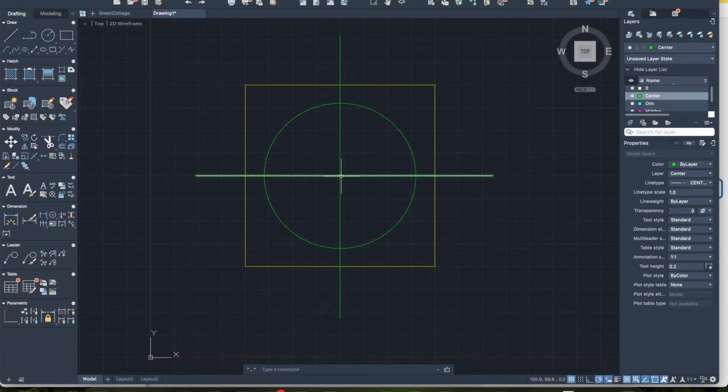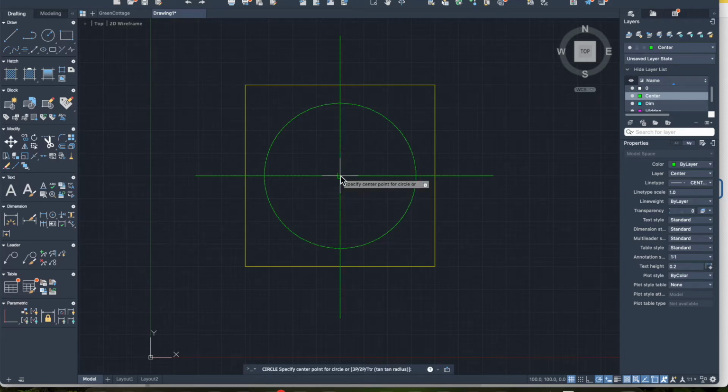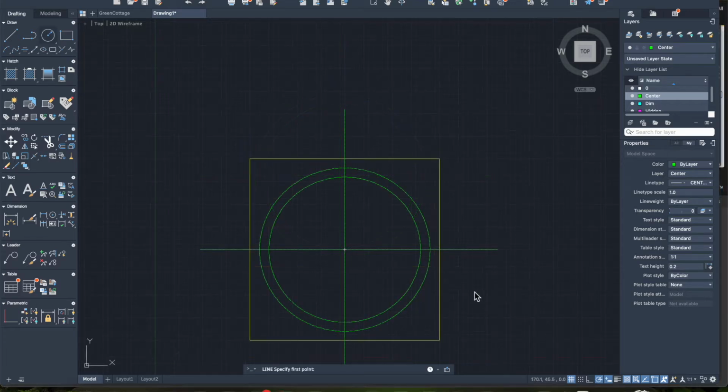And then you can click again in the center. There's different ways to do this, but this is the simplest way to explain. You click again, so hit spacebar to repeat the last command, click here, and this time I want 45, hit enter. So now you've got your circles built, okay? And this distance from here to here is now 50, which is half of the 100 millimeters we put in earlier. Top of our Lego block, this little section that protrudes at the top.